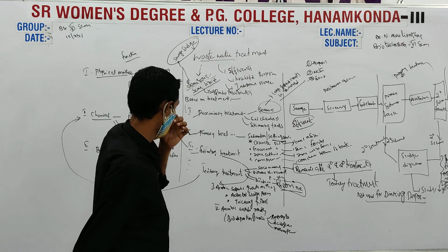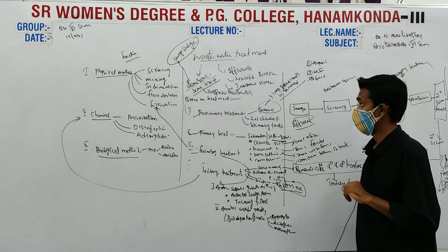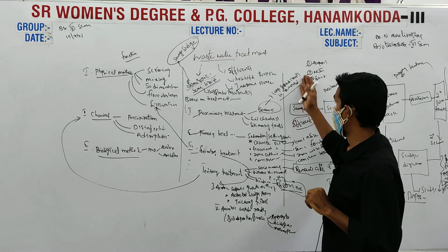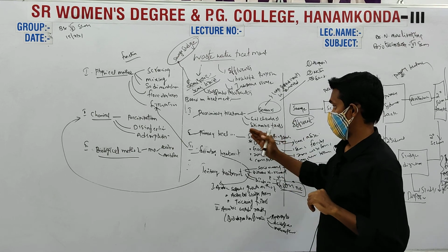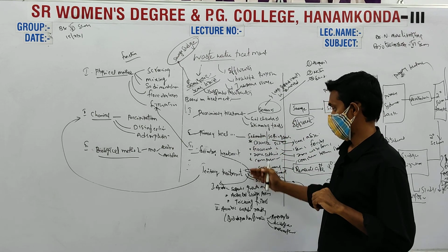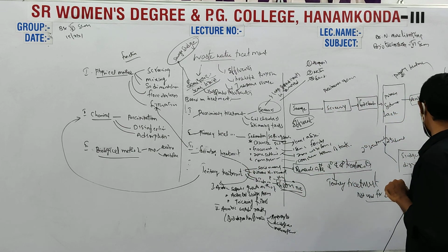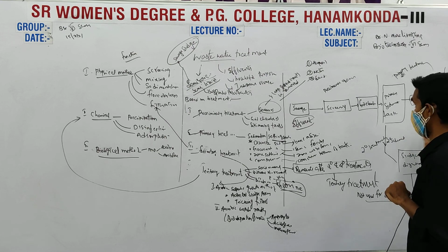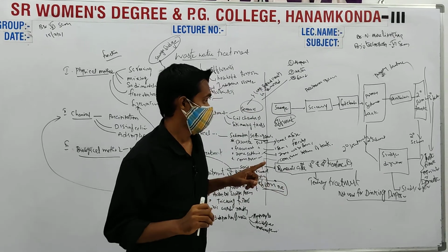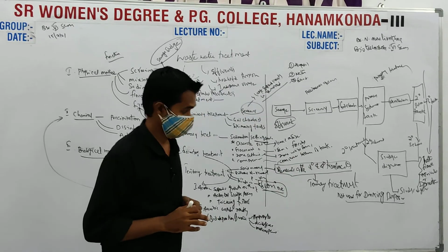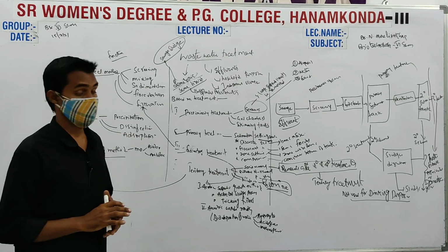Preliminary treatment includes screeners, where large suspended particles are removed, grit chambers and skimming tanks. Overall, the water coming from this treatment will enter the flowing water, which is used for agriculture or domestic purposes, and not for drinking. So this is all about wastewater treatment. Thank you.